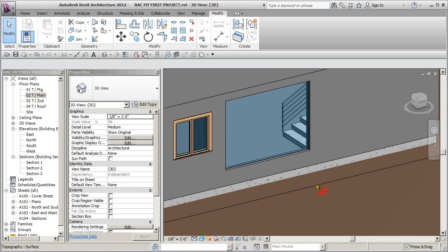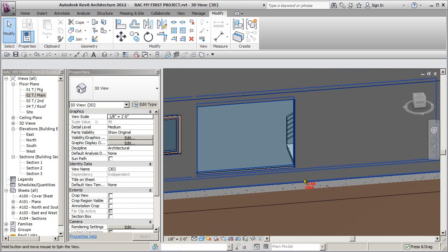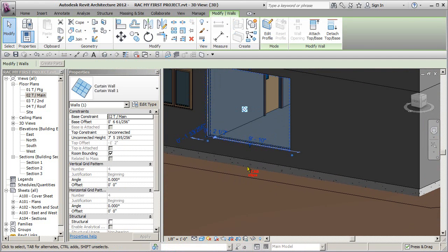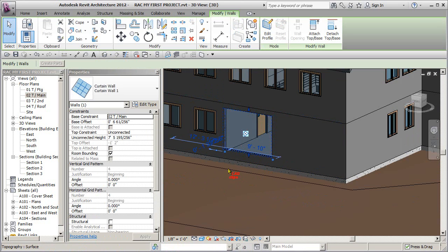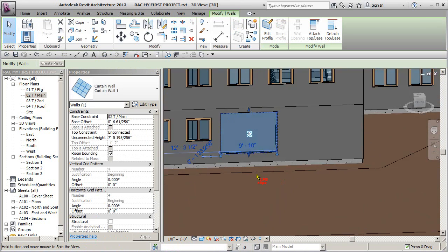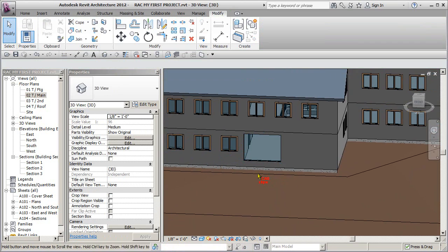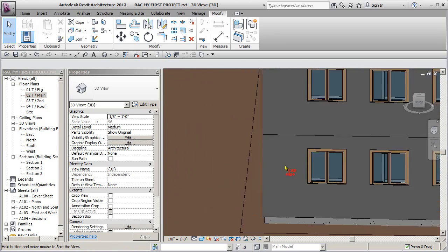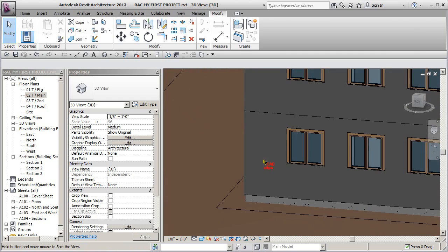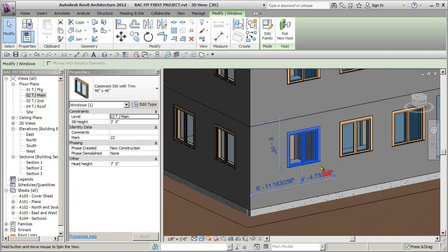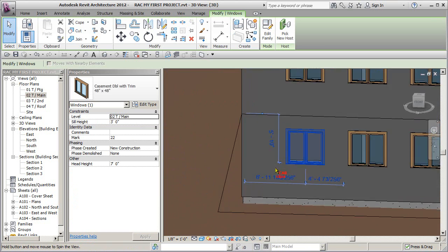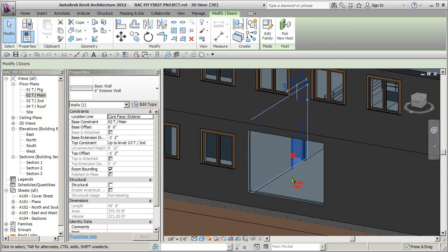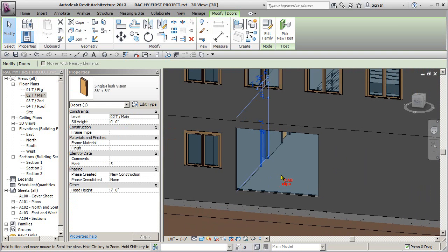Okay, go to my 3D view. There it is. Okay. So now what I'm going to do is, it's the right width, it's the right height. When you swivel in 3D, if you select something and then shift middle mouse button, you will swivel around that point, as opposed to just swiveling randomly where you're not centered. If you're over here and you try to swivel, all of a sudden it goes out of your view. But if you pick something and then you swivel, it'll actually turn based on that vertical Z axis. So when you're swiveling around here, pick something and then you'll turn around that point.